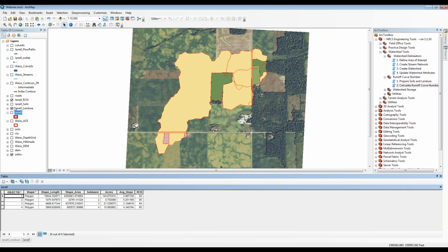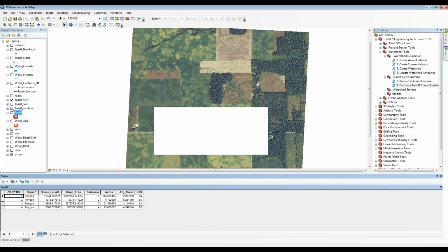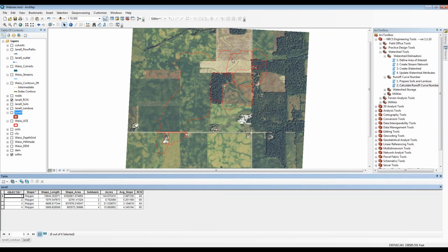I'm going to turn off these layers, our land use layer, our runoff curve number layer. This layer here is an intersection of soils, land use, and subbasins. That's where all these polygons come from. No, runoff curve number, yes, sorry. I'm going to turn it off because I never used that layer. I'd much rather see my curve numbers added to these labels.